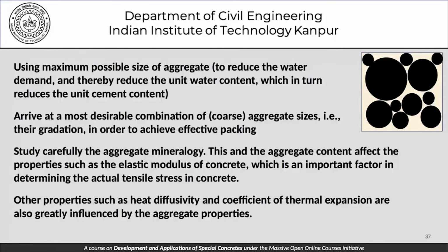Carefully study the aggregate mineralogy. This and the aggregate content, we've already seen this picture before, affect the properties such as the elastic modulus of concrete, which is an important factor when it comes to actually determining the tensile stress in concrete.